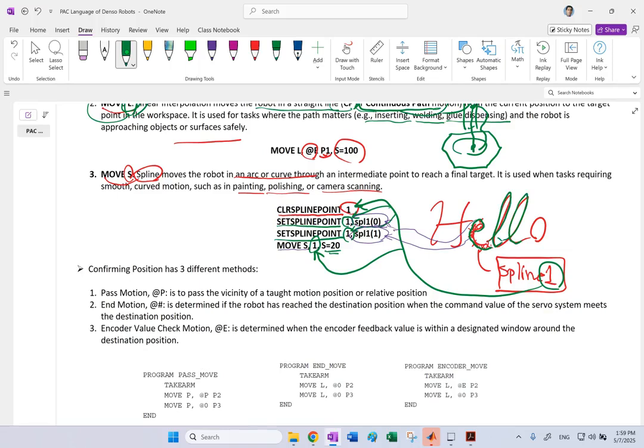And remember that when you use splines, if there is a sharp corner, you have to switch the spline. So here I can say this is one spline, but because here I have a sharp corner, I'm not going to call this flat line to be a part of that spline. So if this is spline 1, here I have to terminate it. If I start it here and end it here, this is going to be the start of the next spline. This is going to be the end of the next one.